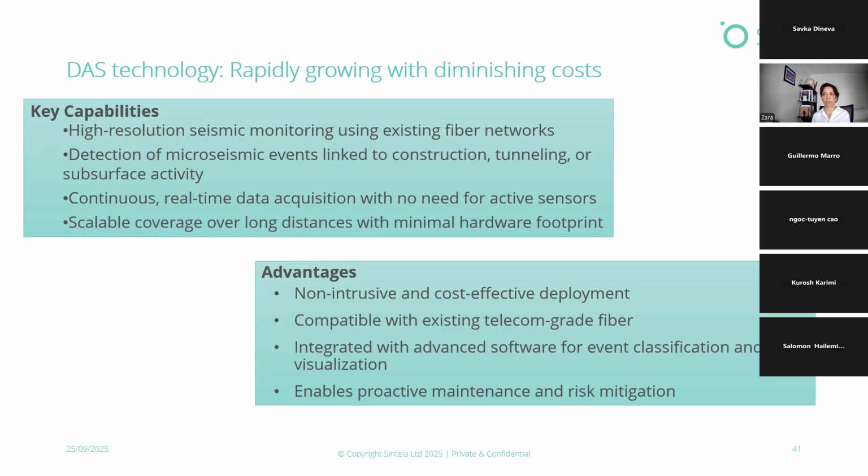It enables the detection of microseismic events for subsurface or for civil projects. The system is continuous and real-time, and there is a lot happening also on the real-time processing of seismic events with DAS. There has been some good work done with ETH and a few other groups in that area. And then there is really scalable coverage: it's fairly easy to deploy fiber optic cables over long distances and get measurements in real time.